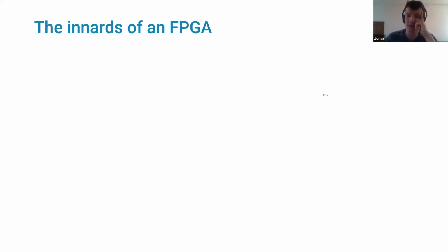So I originally built my master thesis for a ZU102, and it barely didn't fit. It used the resources of a ZU102 exactly, which meant it didn't fit, because if you use the resources of an FPGA exactly, it means you don't fit. So I think about 250,000 LUTs off the top of my head. It's also in the paper, but that is about 1/4 of a U280. So of the final design I'm targeting, it will take up about 1/4.